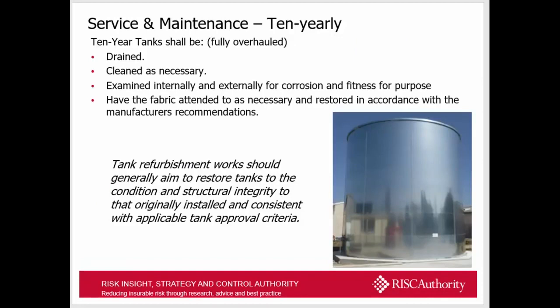Tanks, 10 yearly, again same as the 3 yearly. A 10 yearly tank after 10 years shall be drained. It shall be cleaned internally and externally, examined internally and externally for corrosion and fit for purpose. Again, have the fabric attended to in accordance with the manufacturer's recommendation.